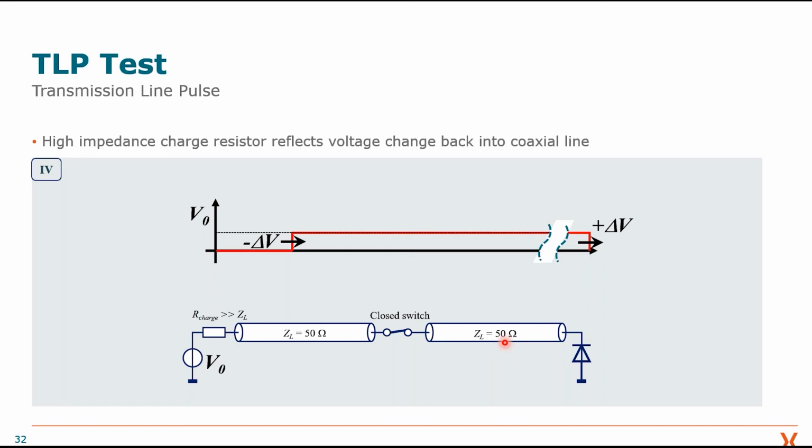And in addition, there can also be big differences between the ESD gun vendors. In order to prevent all of these, this TLP was invented, and this is basically the test setup, or the block diagram of this method.